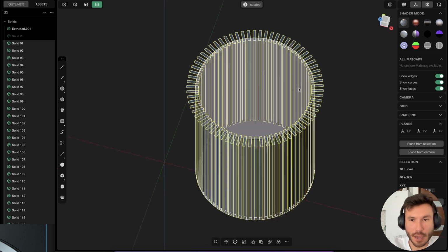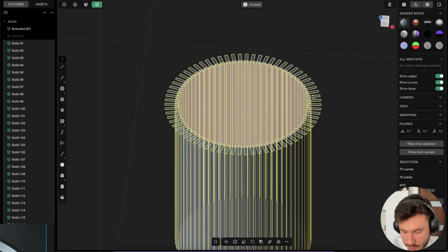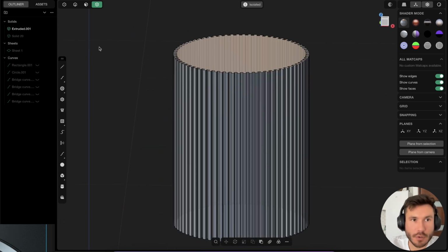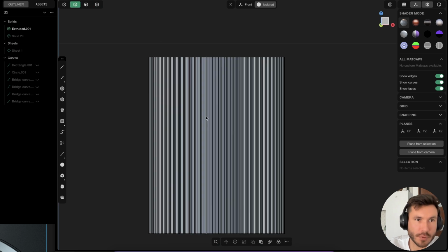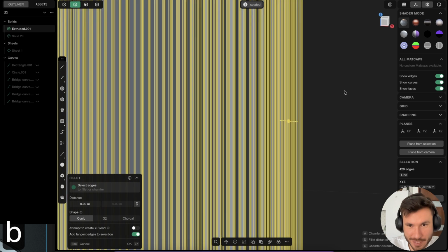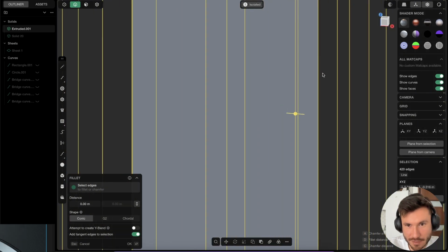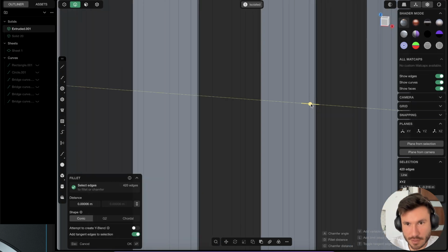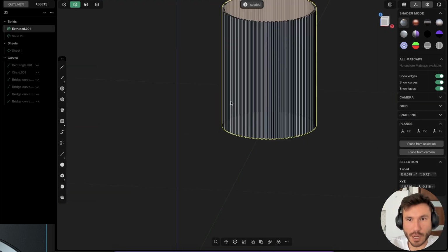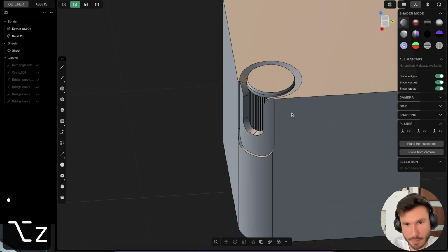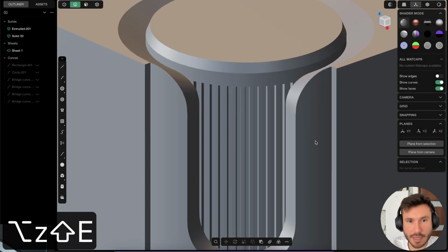So just wait. And now while everything is selected, just press X, because then all the curves and all the cut bodies will be removed. And you can now also just go here to the front view, press 2 and select from right to left all edges. And if you want, you can give them a nice tiny little fillet. So you really have to zoom in. You see you give everywhere a nice little fillet, zoom out, deselect the object, press the dot again. So you bring everything back and you have something like that.